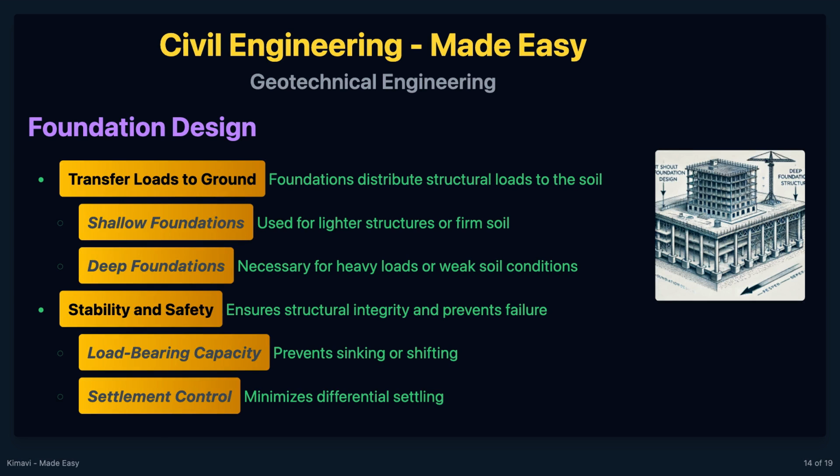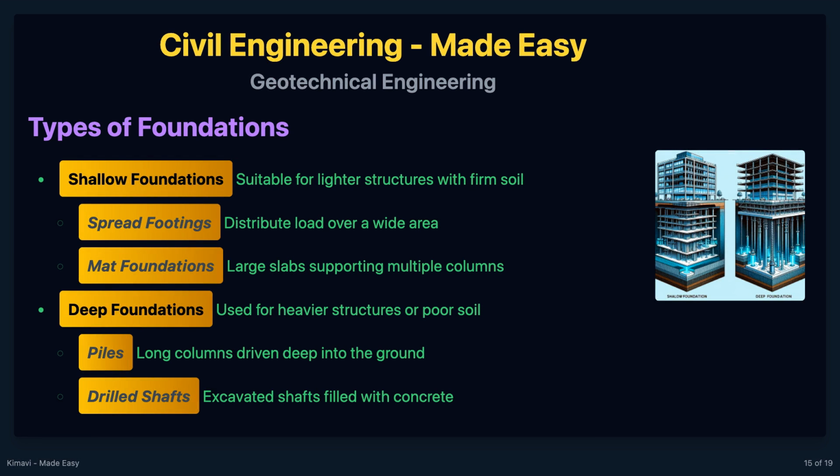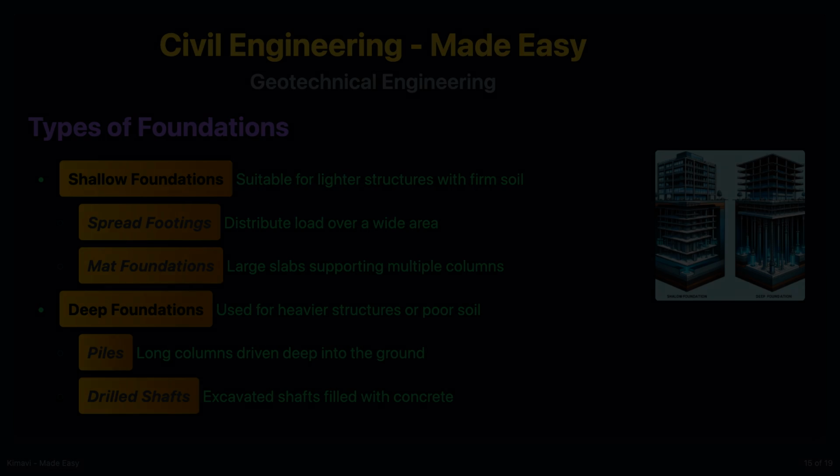Foundations are structural elements that transfer loads from buildings or other structures to the ground. Proper foundation design is crucial for the stability and safety of structures. There are two main types of foundations. Shallow foundations, such as spread footings and mat foundations, are used when soil near the surface has sufficient bearing capacity. Deep foundations, such as piles and drilled shafts, are used when the surface soil is weak and loads need to be transferred to deeper, more stable soil layers.